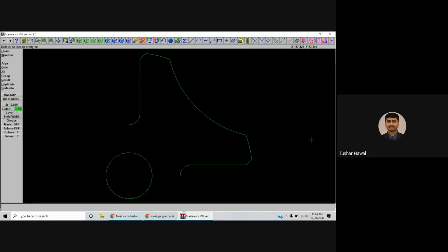So now the geometry is ready and that can be mirrored. Okay, now let me have a reference line for mirroring. Create a line horizontal from the origin, that is 0 0. I'll create a very big line, say enter. Similarly, I'll create a vertical line. Create line vertical from the origin vertically a big line, enter. Okay, so the line is ready, across which we can mirror the things.